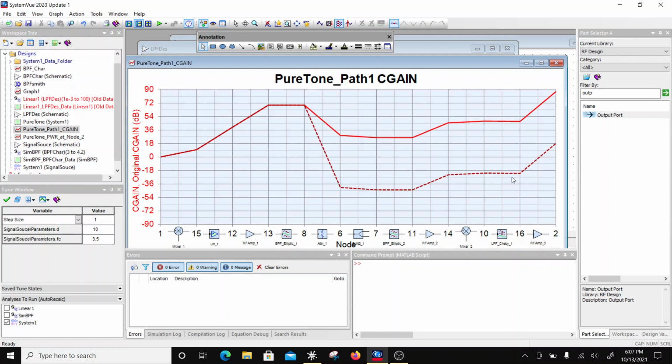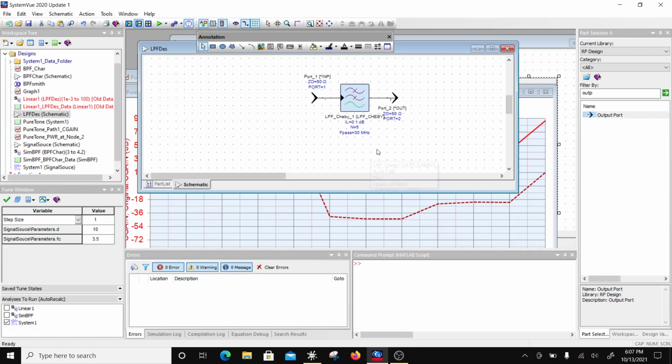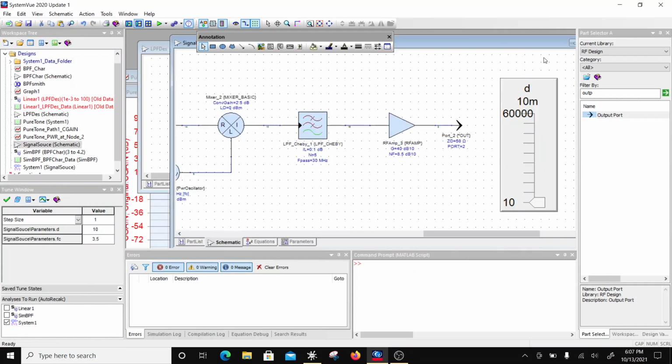And similarly this final amplifier, which is 47 dB, 47.3, and this one is 87.2, right? So this is 40, so this is again 0.2 dB compressed. Okay, so everything is going to go through compression if you are hitting on the high side. Now this is not what the power levels are going to be, because 45 is too high. It will just saturate out from rail to rail. So that's not what is going to happen.